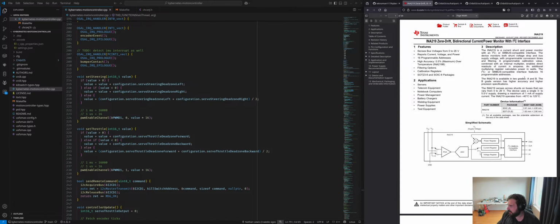If we were to say have a full 12 volt drop across the resistor, divide that by 0.008, it's huge. You measure a large amount of current can pass through without wasting too much power, or I squared R, I think, is the power loss. Either way, with the higher precision INA219, the B variant, you can use a smaller value shunt, so you waste less power.